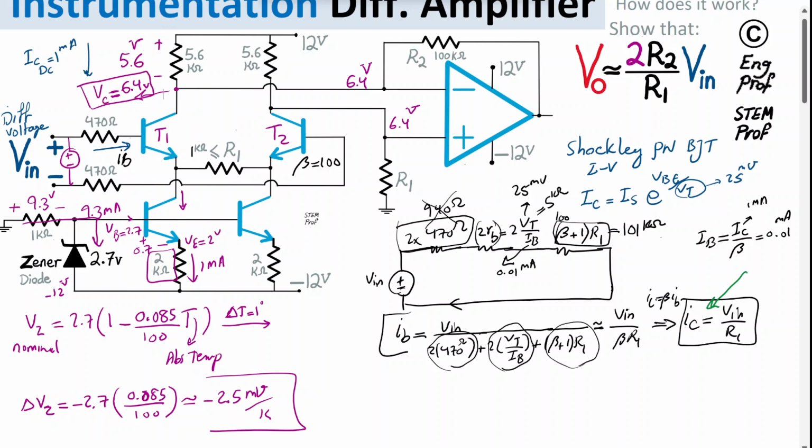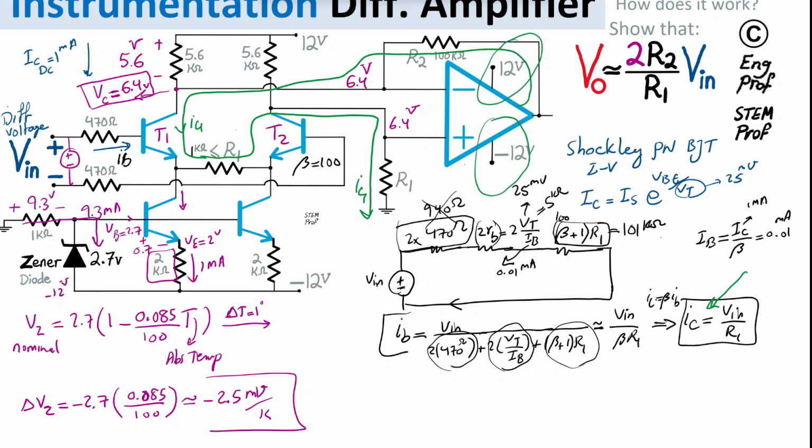So what happens is, effectively, this IC1 can only go like this. So it can only go through this branch, come down. So this is the IC1 we just talked about, and then go through this branch and then downward through this resistor. So what happens is, since we apply the proper supply voltage, negative 12 volt and 12 volt, to this op amp, and since the op amp has negative feedback, output connected to input negative terminal, the op amp is operating in linear region, not saturated.